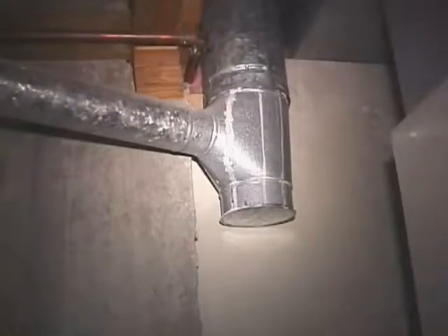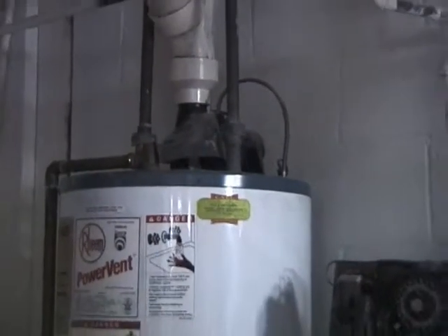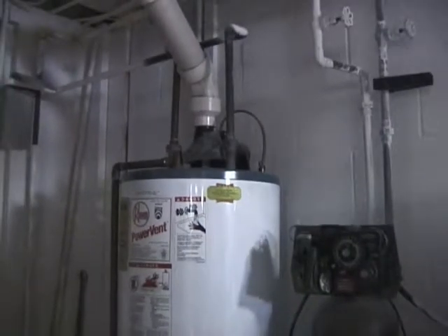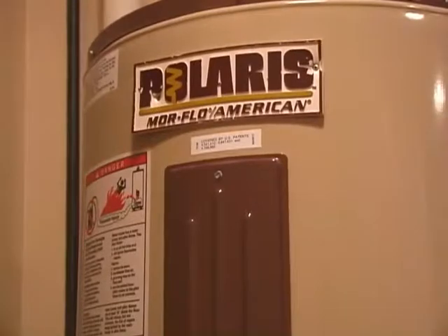At Comfort Institute, we strongly recommend that you not ignore this problem when installing a replacement high-efficiency furnace. Either revent the water heater or sell and install a new Category 3 sidewall vented water heater. Another option is to recommend a combination water and space heating system that uses one vent.